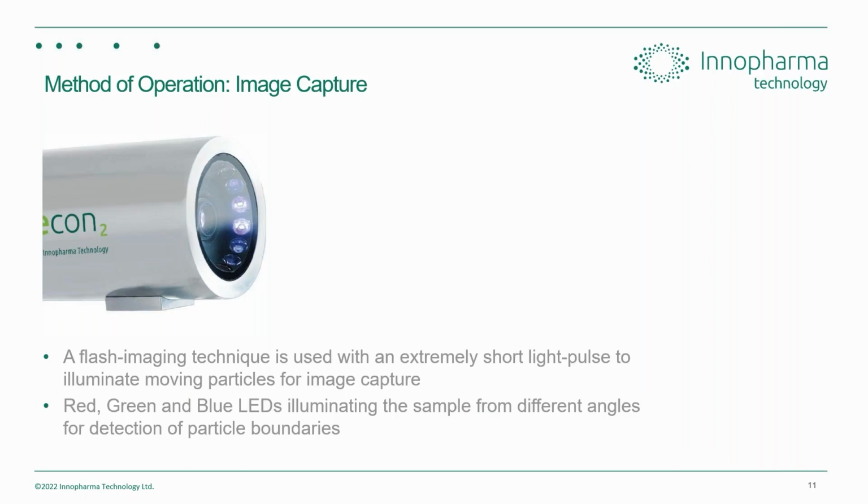The Eyecon 2 uses a camera system with a front lit illumination source of red, green, and blue LEDs. Essentially, all vision systems have to meet a certain criteria of ascertaining images that are well focused and well illuminated. That's really what you need to start your image analysis before you do anything. You have to ascertain you get good quality images. So be it a different vision system that you use, you have to make sure your lighting source is correctly illuminating the product you want to grab an image of.